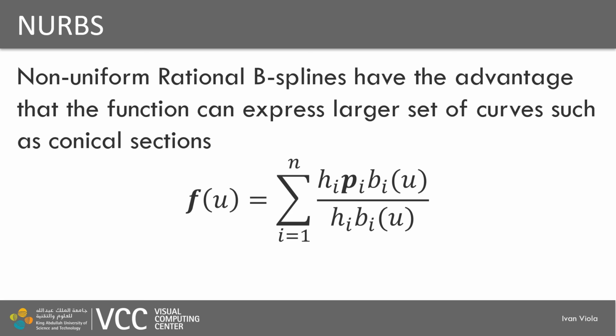The non-uniform rational B-splines are another extension of the B-splines. So we have the non-uniform ones, meaning that our knots can be multiplied and can then form, for example, the interpolation of the starting or end points. And then we have an additional extension, which is called a rational B-spline. From there, this abbreviation NURBS comes from,